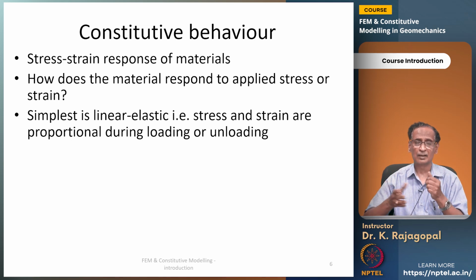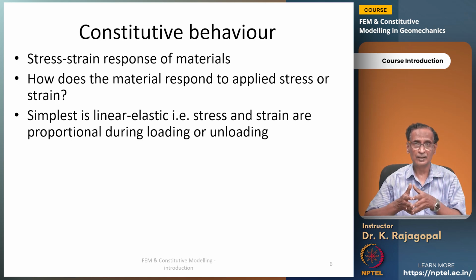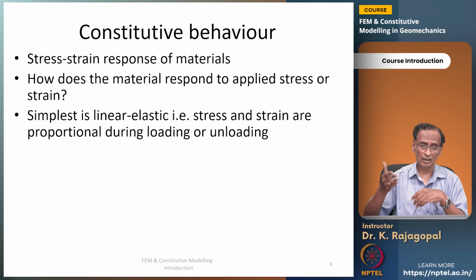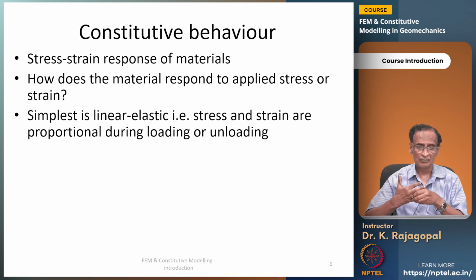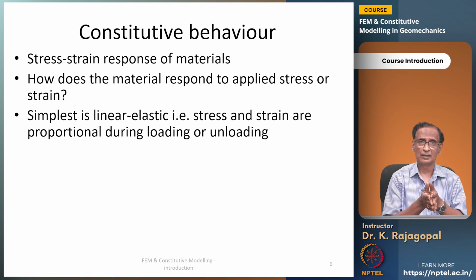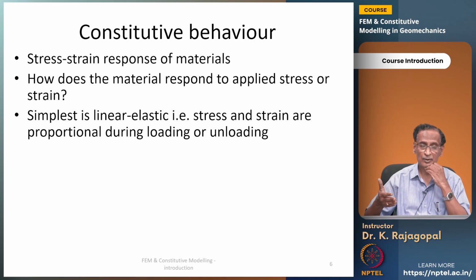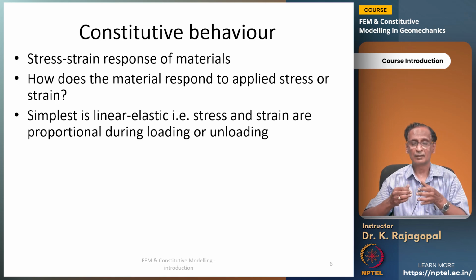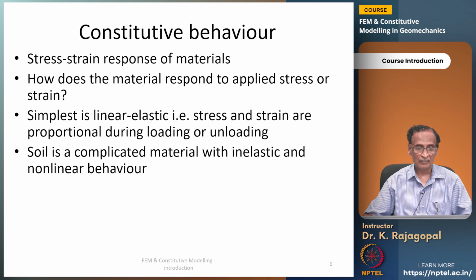One of the simplest constitutive models is the linear elastic, in which the stress and strain are proportional to each other during both loading and unloading. It's the simplest type of model, and especially when we are doing any closed form solutions like the elasticity solutions, they are all based on simple linear elastic analysis.